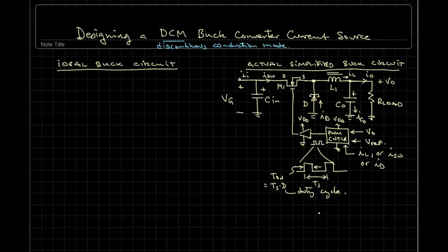Essentially in that PWM controller, if you're trying to regulate the output voltage, which is how I've drawn it here, so that the output follows some voltage reference, then the duty cycle on the switch will adjust itself so as to drive VO to VREF, much like the throttle on your car would be adjusted to maintain some speed that your cruise control would be demanding.